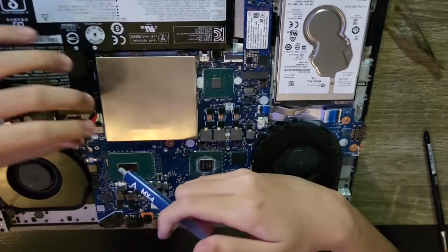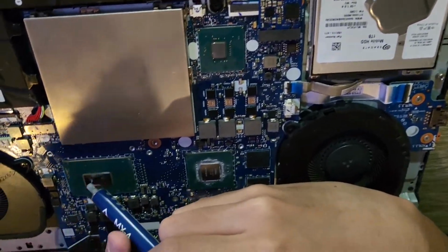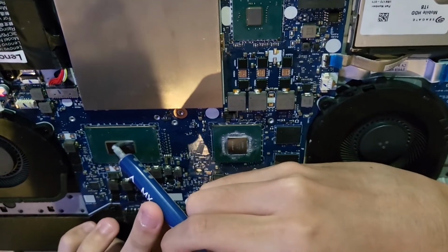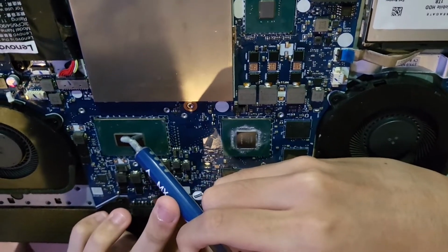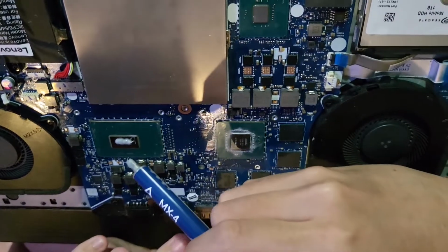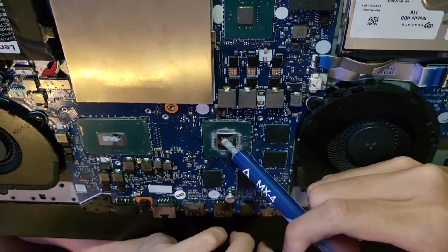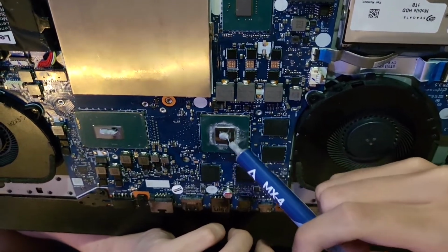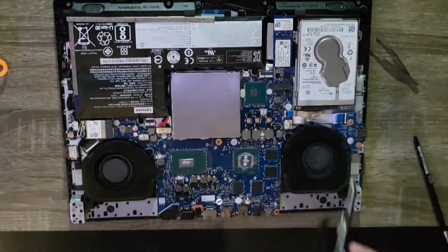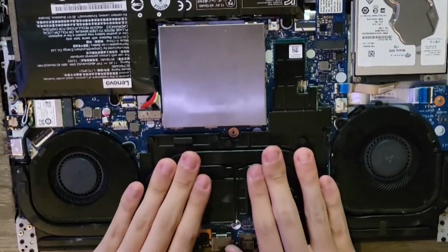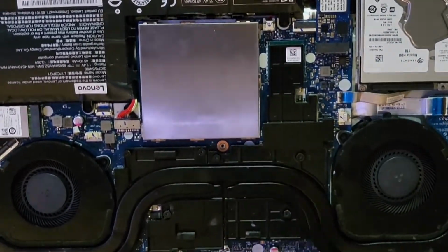Third, slowly apply the thermal paste to the CPU and GPU and make a small rice shape as shown in the video. Make sure you apply the correct amount of thermal paste. Too little will cause lower surface area covered and overheat. Too much will also cause less direct contact between the CPU and the heatsink. Fourth, place the heatsink back into the original position slowly to even out the thermal paste and screw it in. Put the back cover on, screw it evenly, and your laptop is freshly thermal pasted.